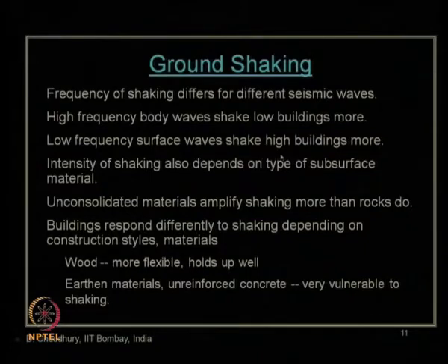So, the common layman idea that tall story buildings are always more vulnerable during an earthquake is not always true. It is true only when the input earthquake surface wave, caused during the release of earthquake energy, has a low value of frequency. Then only the tall story buildings are more vulnerable to damage. Whereas, if it has high frequency body waves, then low rise buildings, even a single story building, will also be more vulnerable to destruction due to the earthquake.